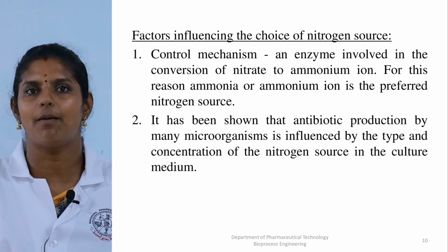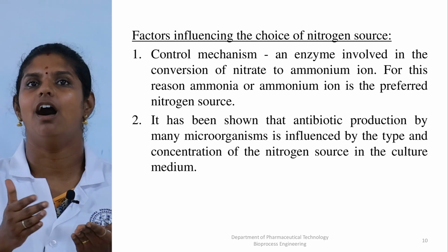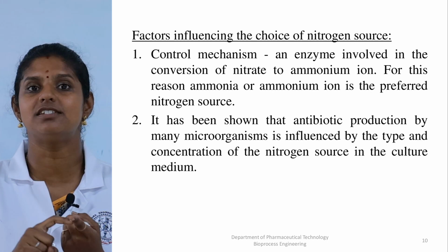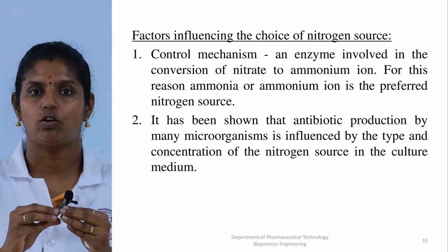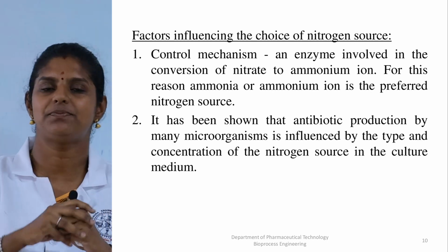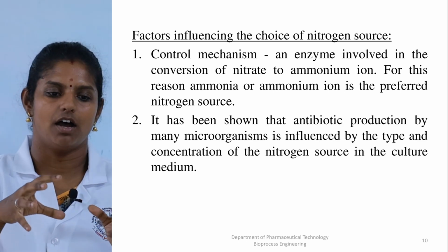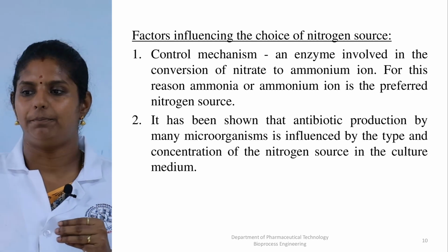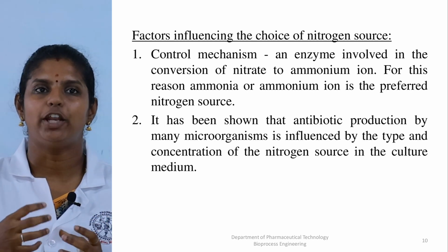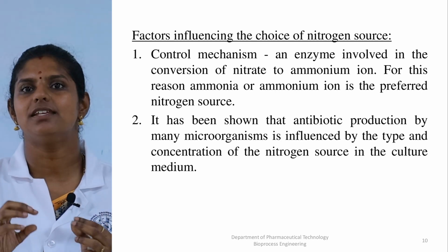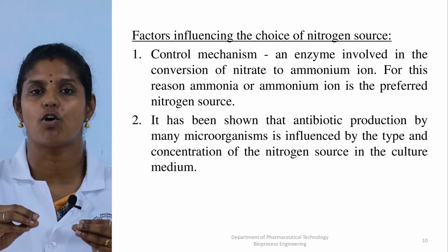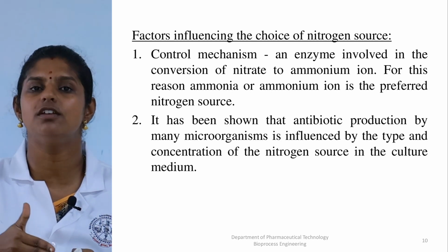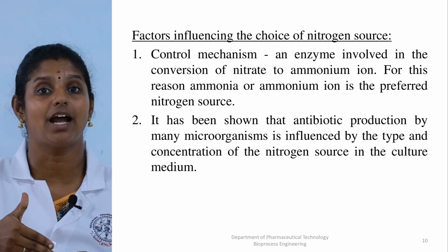Next we are going to see what the different factors influencing the nitrogen source are. One, the main factor, is the control mechanism. When we see it as a control mechanism, certain enzymes are added to convert the sole carbon nitrogen source into ammonia for further use in the production process. And then in antibiotic production, many microorganisms are influenced by the type of nitrogen source present in the culture media. So the selection of the nitrogen source is also one important factor to be considered while